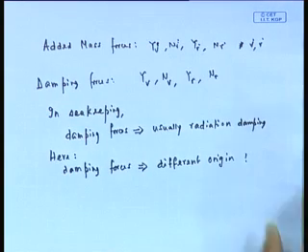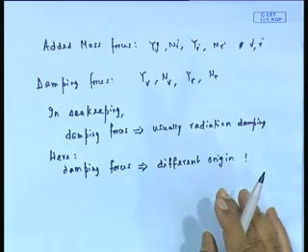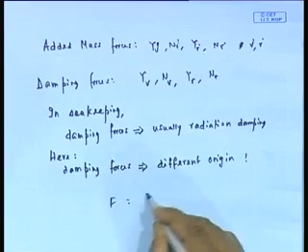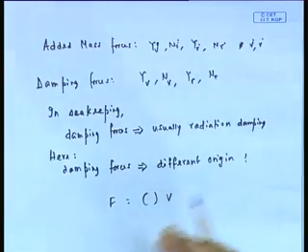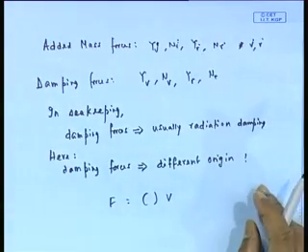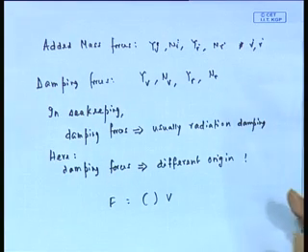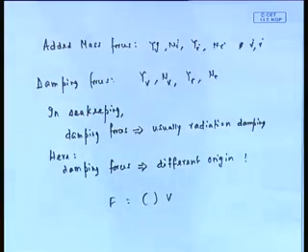The reason I want to tell you is that essentially in fluid mechanics, this is another thing that you should understand. Any force that is proportional to velocity, that means any force where you write something into velocity, you normally call it damping force. The word damping is a very generic term. If it is proportional to acceleration, you call it inertia force. In any equation of motion, mass into acceleration is called inertial force.